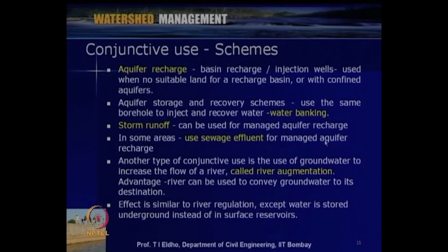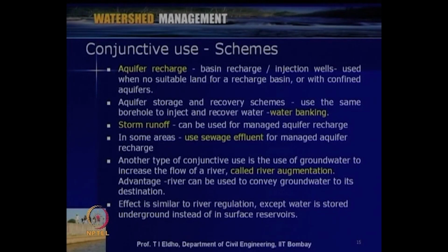In many locations, especially in semi-arid and arid regions, we utilize sewage effluent for recharging. And while recharging, when this treated water goes through the aquifer system, a lot of water quality improvement happens through various processes like biological activities and filtration.